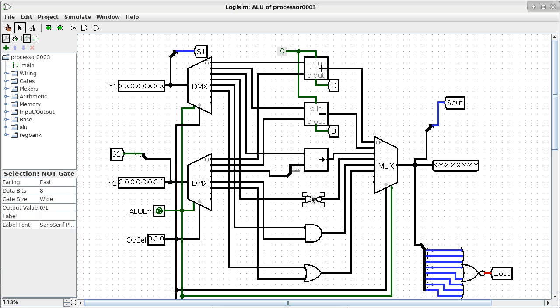This is a negator, but it's an 8-bit wide negator. It negates all 8 bits. It's a bitwise NOT operator. This is bitwise AND. This is bitwise OR. So these are representing all the basic calculation support that we have. This is it. It cannot do multiplication or division without actually coding it. But this gives us all the basic stuff that we need to implement multiplication, division, and all the difficult math stuff that we need to do.